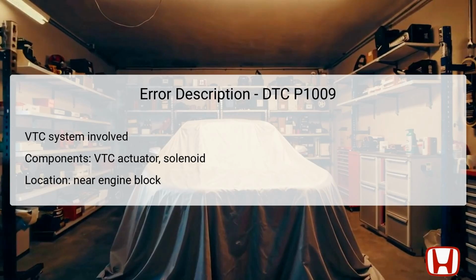The VTC actuator is typically located near the engine block, often on the camshaft or timing chain cover, depending on the engine design. Its function is to adjust the timing of the camshaft based on engine demands, influencing valve opening and closing times. Additionally, the VTC oil control solenoid valve A regulates the oil flow to the actuator, thereby controlling its movement. A malfunction in any of these components can trigger DTC P1009, indicating a need for further inspection and troubleshooting to identify the root cause of the issue.